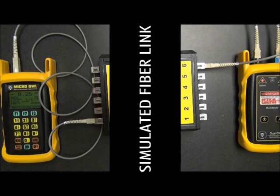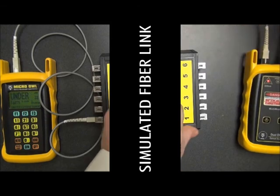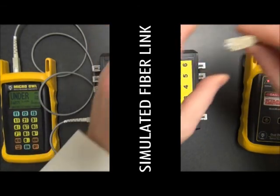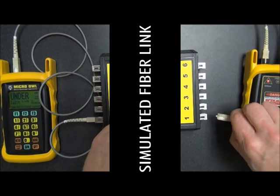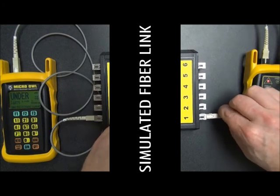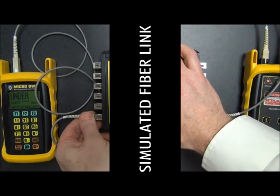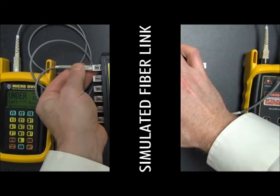But since we're testing at 1300 as well, we're going to test using the 1300 nanometer reference cable on a light source. So we can disconnect the 850 nanometer reference cable. We're done using that one. And we grab the 1300 nanometer reference cable here and plug into port number 1 again. Okay, and also with the micro OWL's reference cable, plug it into port 1 as well.